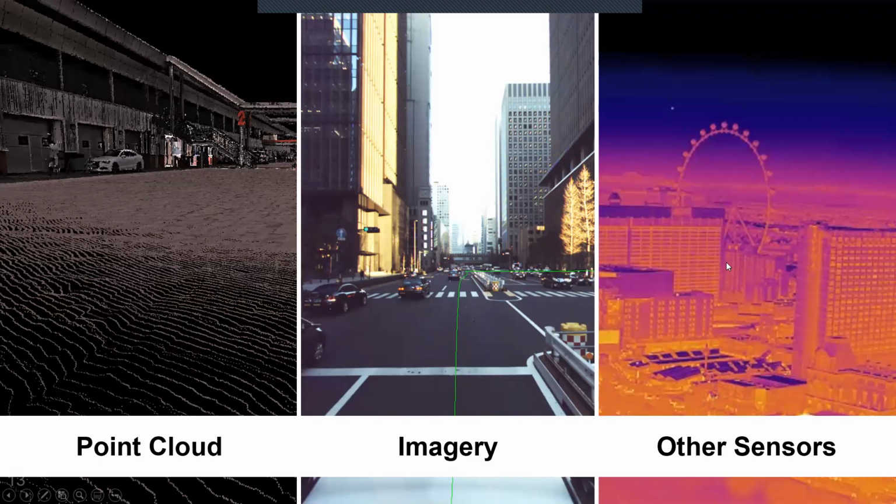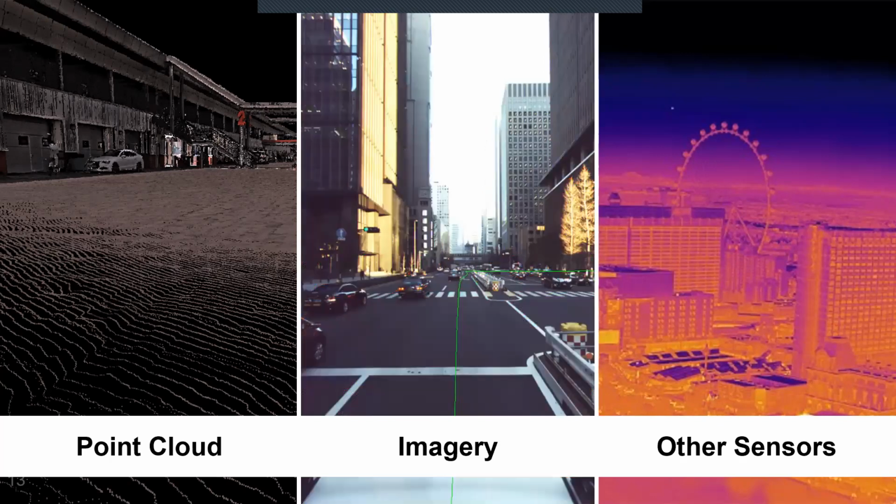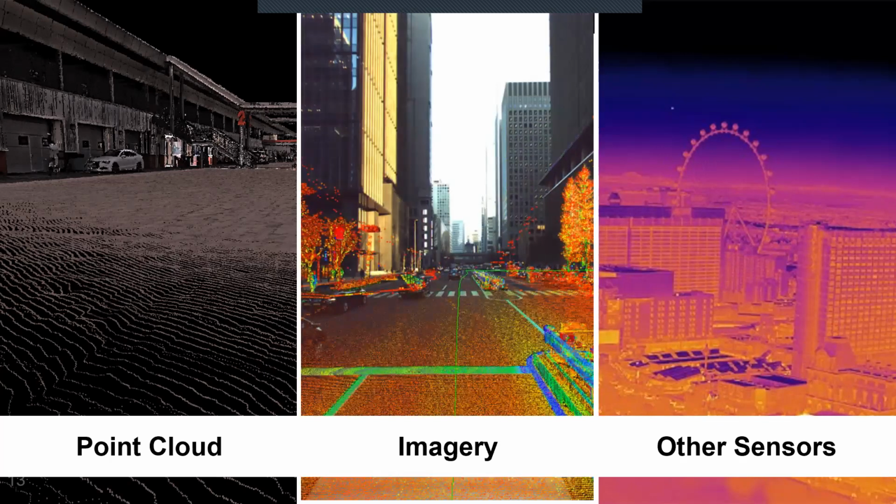And then you have additional sensors like pollution sensors, temperature sensors, humidity sensors. All those sensors can also be attached over the area, and these areas will get different information. In that case, the sensor information will be provided by the secondary sensors. And what the software does is merge the data together. If you see in this imagery, in the center, it puts all those laser dots over it. So now you can see the image as well as the point cloud together.